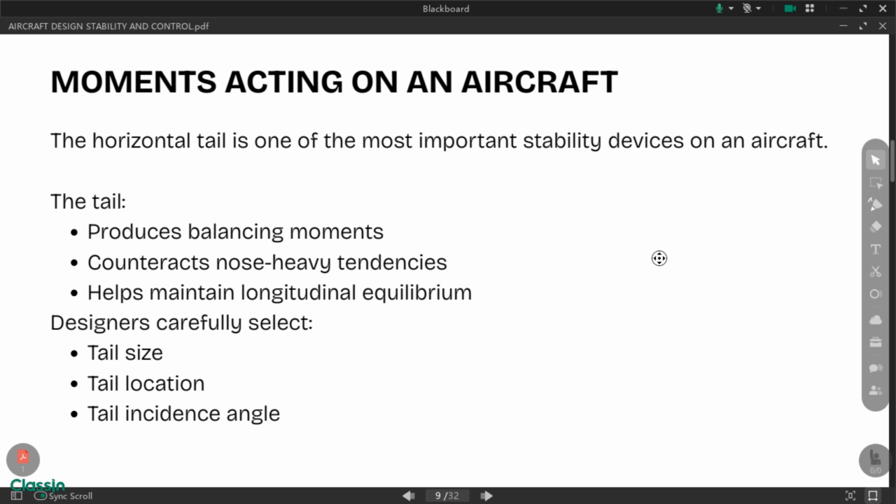Okay? So yung mga aircraft natin, most conventional aircrafts, they are designed dito with the center of gravity ahead of the wings. Tama? So naturally, yung arrangement na yun, it would create a natural nose down tendency. So to counteract yung tendency na yun na mag nose down yung aircraft, we have yung horizontal stabilizers, no, at the tail to produce a downward aerodynamic force. So because this force acts far from the center of gravity, again, it would create a balancing nose up moment naman.